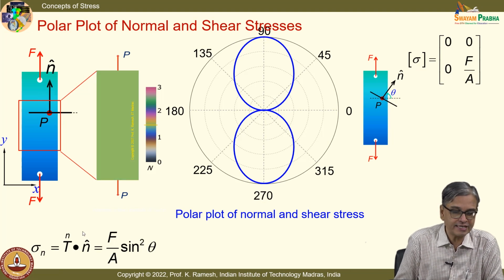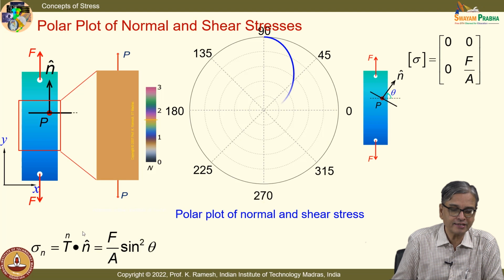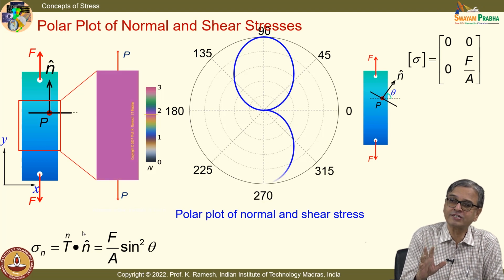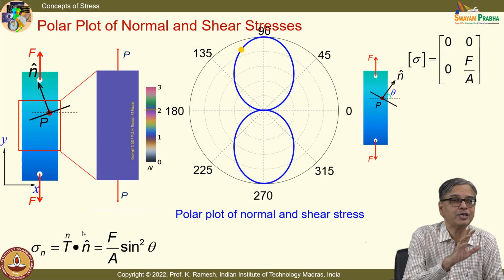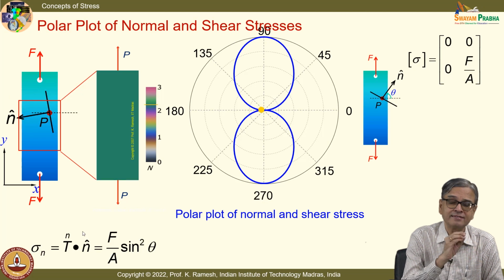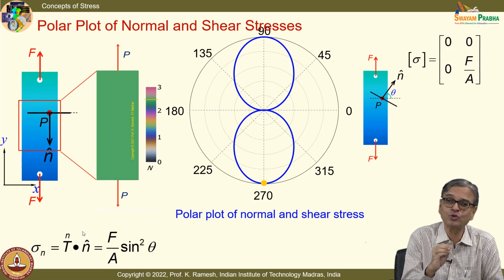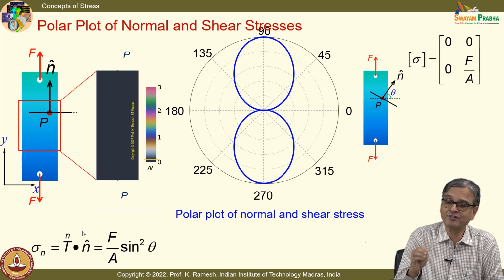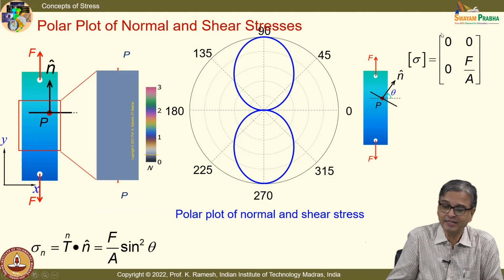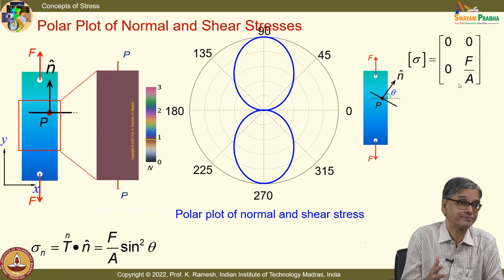And if you want to see it again, you can have a look at it, because now you can associate this with the particular plane. So, a simple tension can throw you surprises like this. In those planes, the representation of the stress tensor that you have written will not have zeros in all the places; it can be populated also, fine.